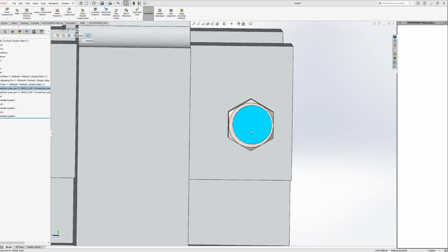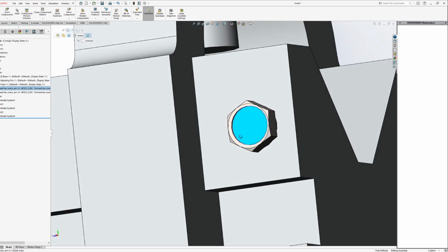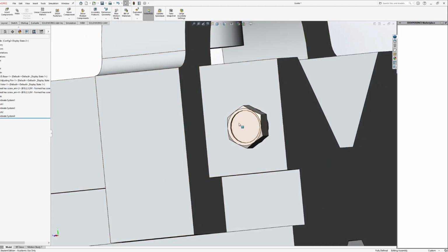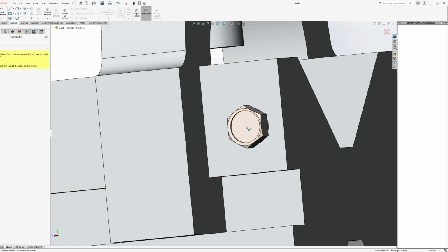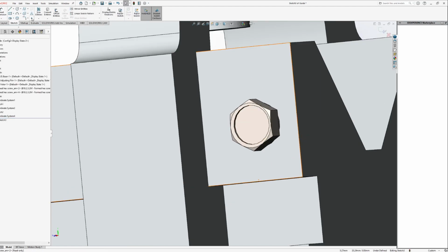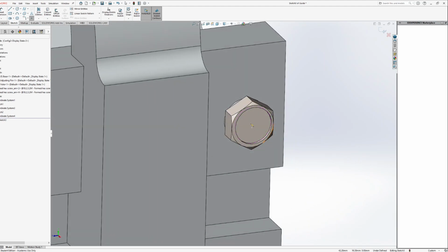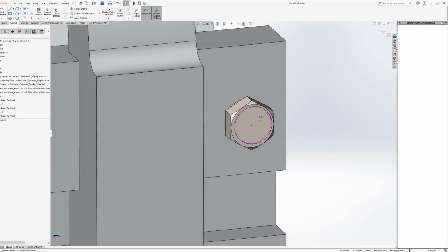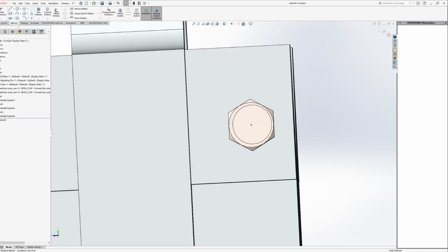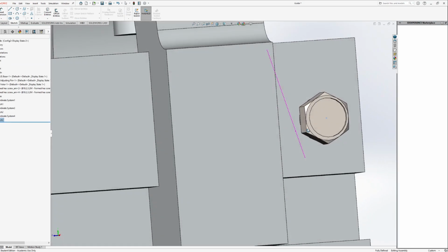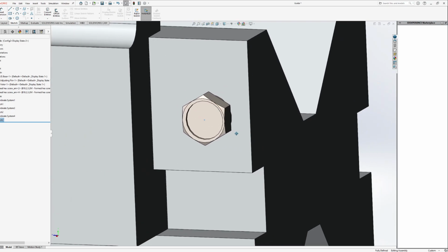So just like how we would do it in a component creation, I would either select that face first or go into sketch, hit sketch, and then select the face, and then just put the point in the appropriate location. So it should show up right like there. And then from there, when you hit exit sketch, it should be a completely applicable point to use.